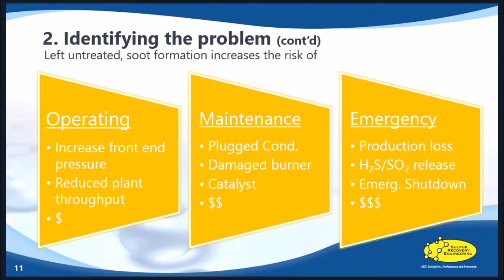That's going to happen. Now, in the majority of cases when we're dealing with soot formation and wanting to use the sulfur wash, it happens instantaneously, relative to a week, a month, or a year. It happens fairly quickly. In the example we're going to use today, you'll see that it happened within a matter of hours. But if it were to happen slowly over time, you're still getting that increase in front end pressure.